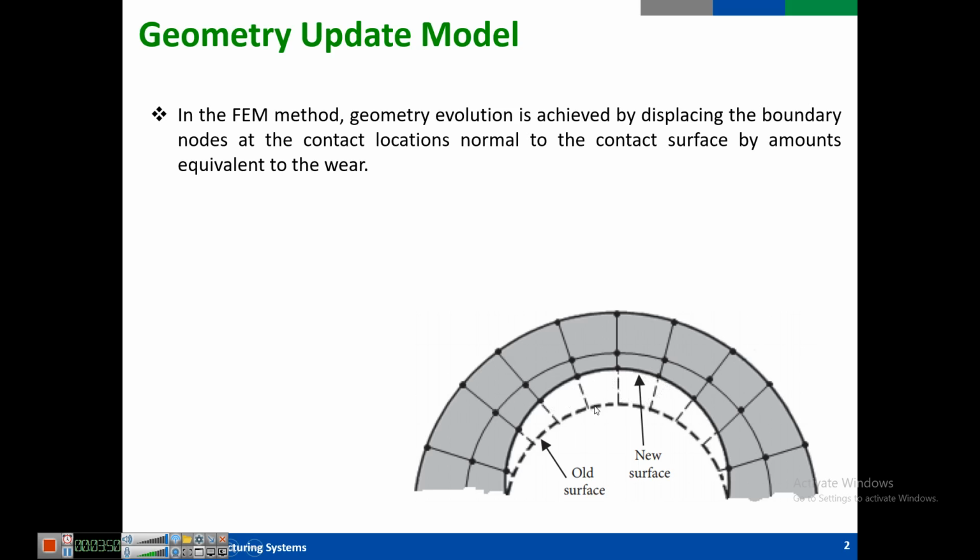In our new surface the nodes move down, based on your wear coefficient and the pressure between, for example, your pin and the deformable plate, for example a disk. And after that you can see the wear depths, based on the information you provide in your UMESHMOTION subroutine.